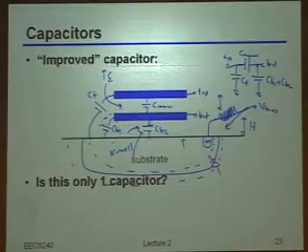So can anybody tell what's the trick I'm trying to play here? And by the way, that bias voltage, I'm going to tell you, is going to make the N side much, much higher than the P side. In other words, I'm going to be applying a strong reverse bias to the diode. Yeah? If you can deplete the N well, then it's not conducting. Well, okay. Oh, wow. You're very aggressive. So you said if I can completely deplete the N well, then I won't have any conduction at all, and I'll have a very, very small parasitic capacitance.